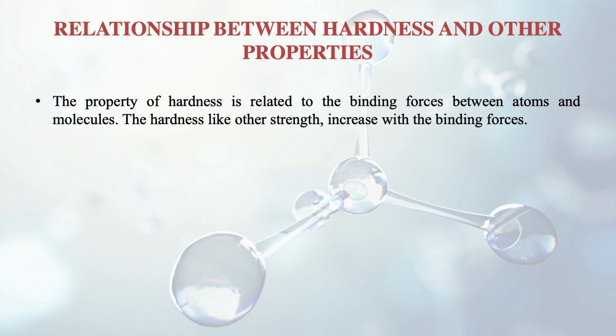Now, after discussing these kinds of methods, we see what the relationship is between hardness and other properties. The property of hardness is related to the binding forces between atoms and molecules. Hardness, like other strength, increases with binding forces. If the molecules inside the material come together and are compact, then the hardness increases, and if they are not, then the hardness decreases.